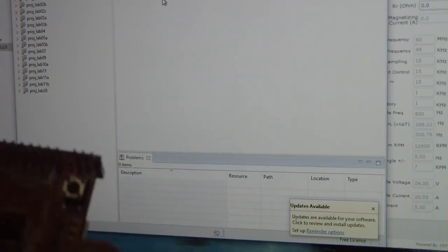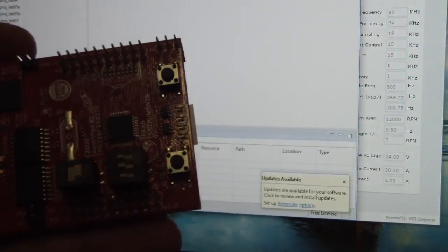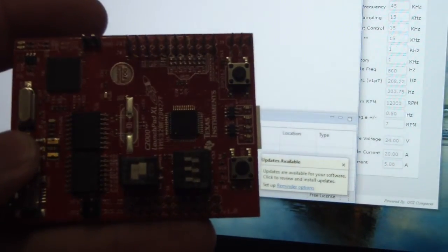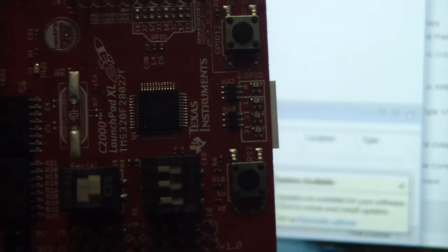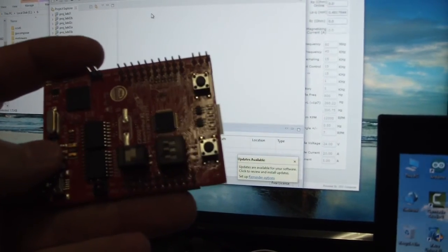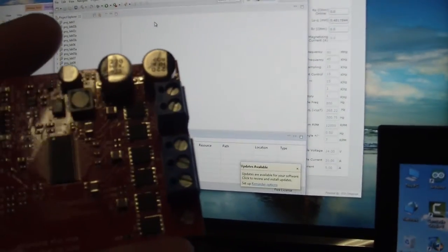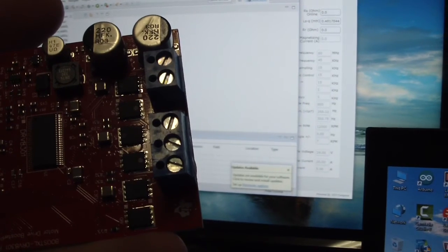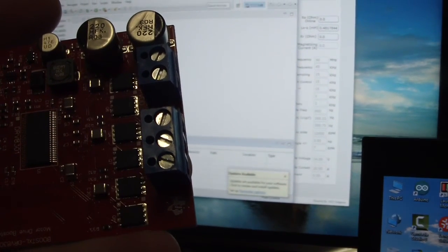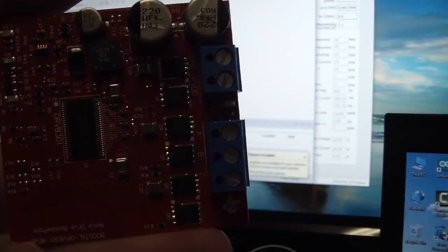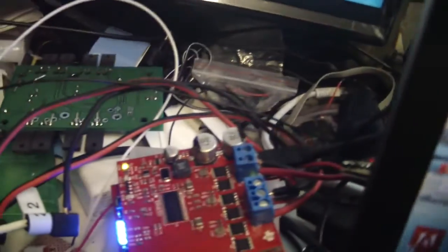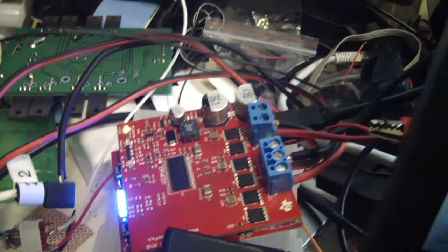And I have here in my hand something that is called C2000 Launchpad of TI. This is a development board with a TI microcontroller and also a USB connection FTDI chip. And I have also over this board, on the top of it, a board which is called DRV8301, which is a motor driver up to 24 volts, about 14 amperes. So it is all connected here, and forgive me for all the mess, because this is how it is when you're working.